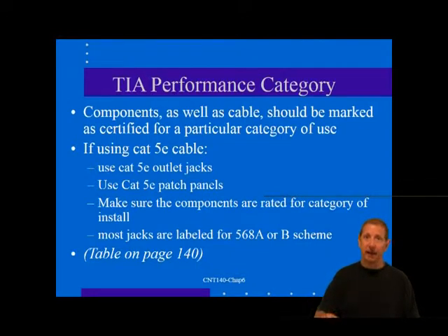However, these technologies need all 4 pair. You cannot very well use 4 pair if you decide to wire just 2, just to save a little money in the short term. It is therefore strongly recommended that any new installation adhere very closely to the TIA standards, including the number of pair to each outlet.